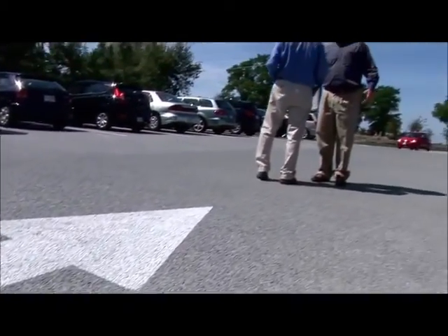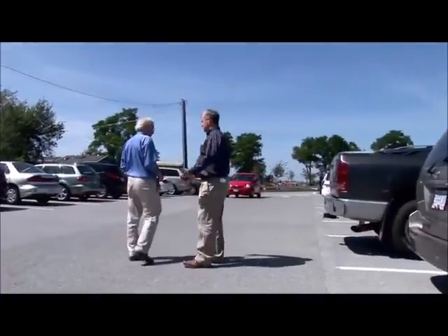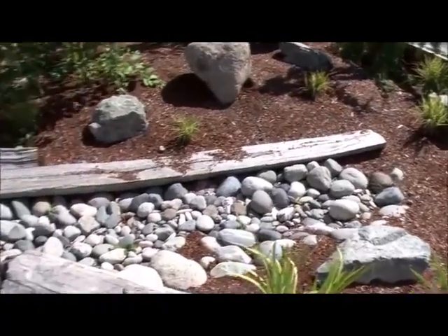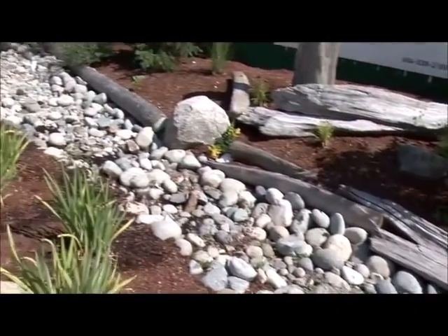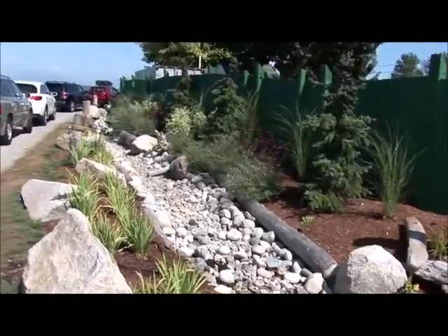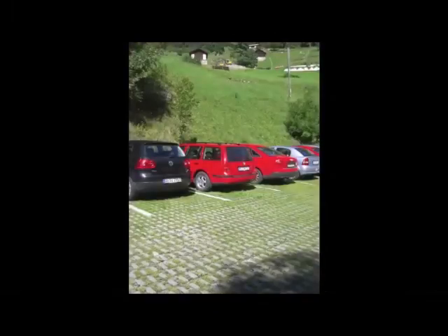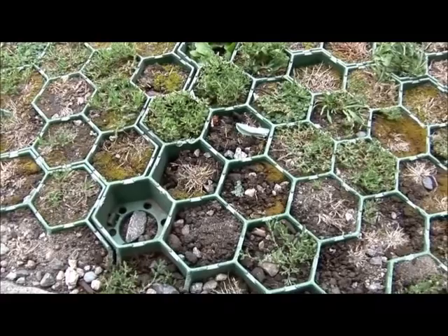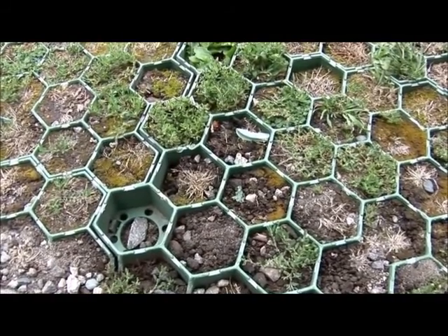This parking lot in Crescent Beach was surfaced with pervious pavement. Pervious pavement can be engineered concrete or asphalt, where fine particles are left out to make it more porous, allowing rainwater to infiltrate right through. This eliminates the need for storm sewers. This site also includes a bioswale to receive any runoff that may occur during large rain events. Other parking lot designs incorporate vegetation right into the surface, as in these examples here. These work similarly to infiltrate and retain contaminants in the soil.